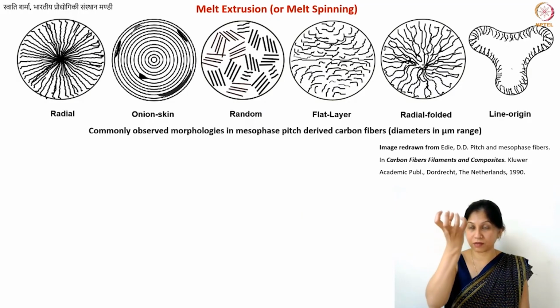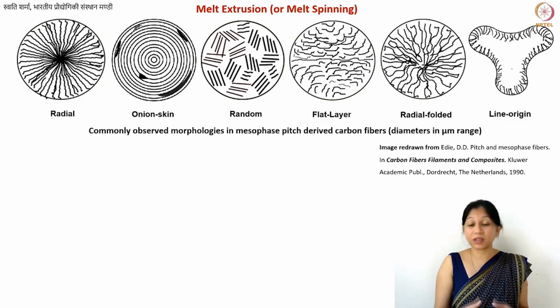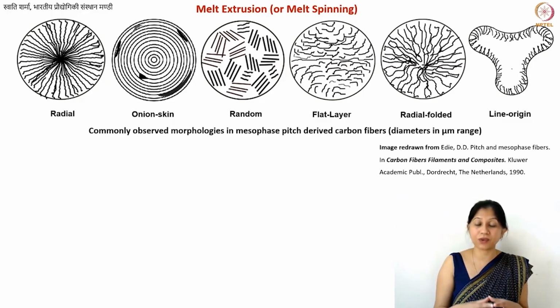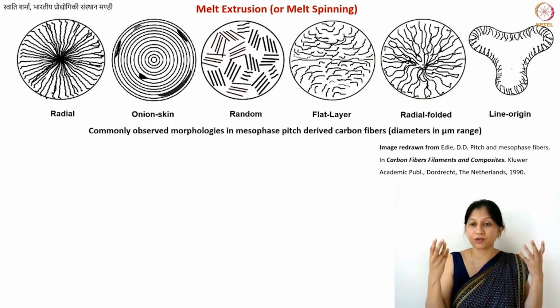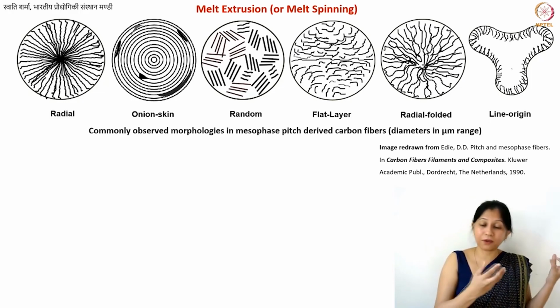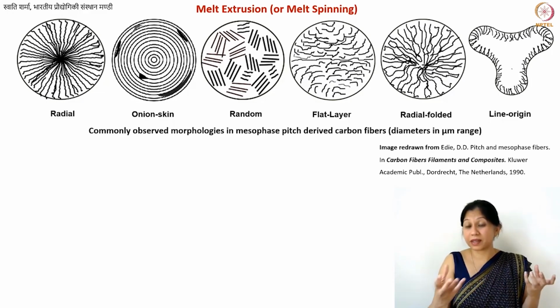from where your fibers were extruded, is not perfectly circular. So you may also have different shapes of the spinneret, and you sometimes intentionally do that because you want to have higher surface area. If you have this kind of fiber shape, then you will have more surface area in the fibers, so your byproducts will anneal out more easily. And also for whatever application you're using, maybe this is a better geometry.